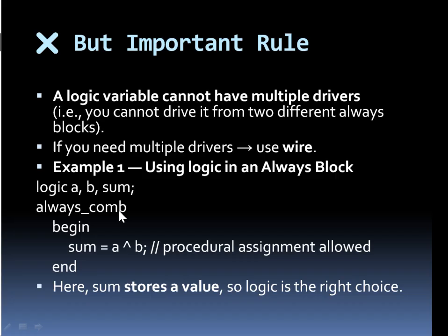Earlier in Verilog we had always at the rate of the sensitivity list. That same thing is used for combinational circuits, flip-flops, latches, everything. But if we use always_comb, it will always infer a combinational circuit. There is one more procedural construct called always_ff. If we use that, it will always infer a flip-flop. These varieties were not there in Verilog. We will be discussing these things later.